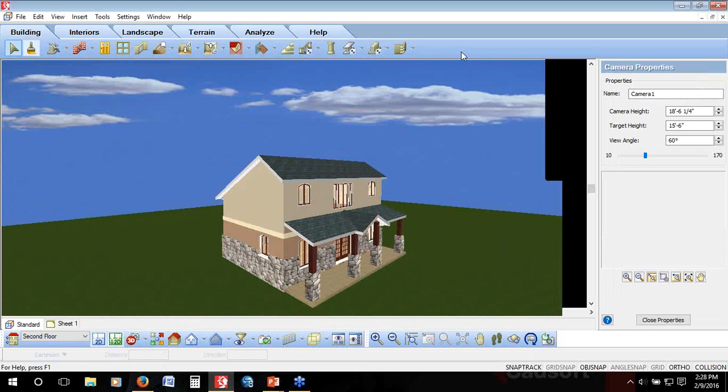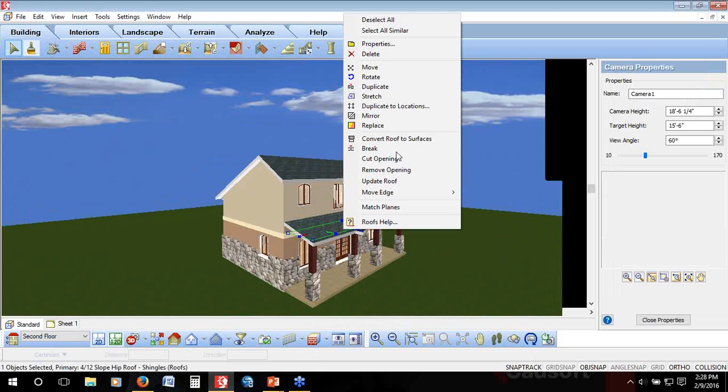Place all the gables around the building as you need to. And then from there, tackle pitch and plate heights of all the various sides, all the different arrows. And if you need to accommodate multiple pitches, multiple plate heights along one side, remember that you can always select a side, right-click, and break into sections so you can accomplish multiple pitches and multiple plate heights along one side.